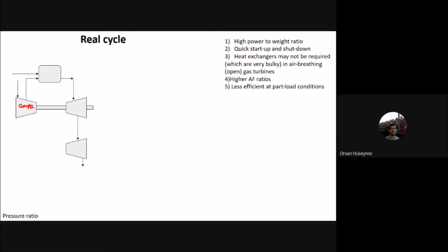Okay, compressor. And into that compressor, you have the air. Air enters that compressor, and it is compressed from, let's say, P1, let's say this is 0.1, to P2. And you should know that P2 is greater than P1, of course, because it is a compressor. When the air leaves the compressor, it gets into this combustion chamber.